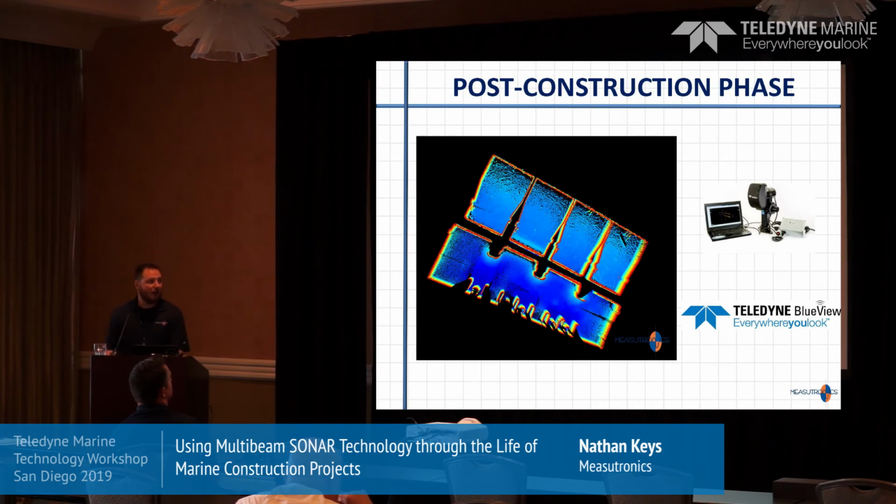So this is a paper intake. It's a paper mill, and they intake water from the Columbia River. And so we dropped the BlueView in on a pole, so not a tripod, but just on a pole this time. And we did a bunch of scans in there, and then we stitched them all together. Basically what they're looking for is sediment buildup, or like you can kind of see in the one on the right-hand side, upper right, there's some logs in there. So if there's material or debris in there, they want to find it and they want to get it out of there.